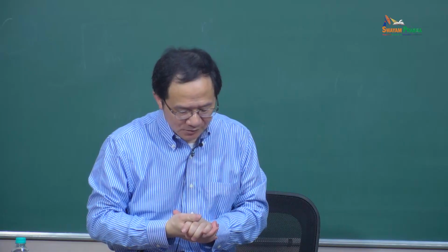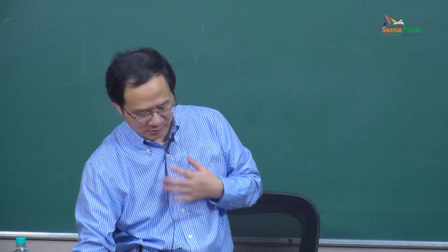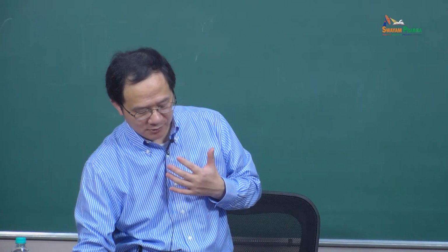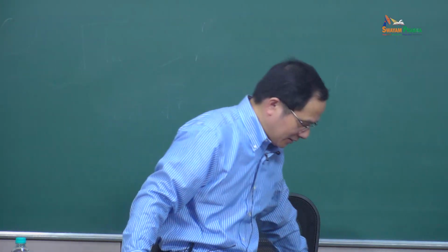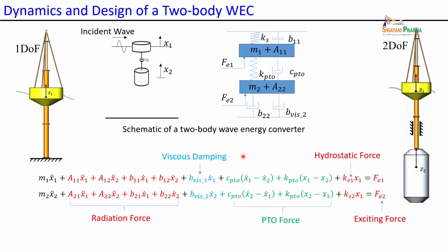Okay. Then the viscous term, and you have first viscosity, second viscosity, like that. And this top part, whether you can ignore it or not, you compare with this part, right? The first mass, the radiation damping is relatively large compared with this viscous damping. We ignore that, simplify that. And the second mass is of similar order, so we don't ignore that.